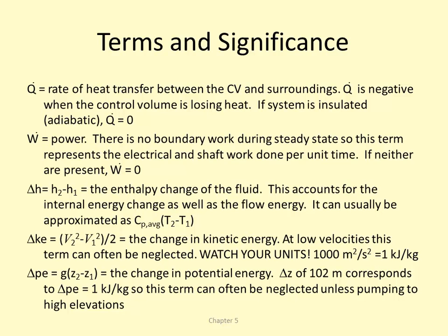Kinetic energy changes, again, watch your units. If velocities are not given, you can assume that you can neglect it. If velocities are given, then you have to calculate it. And the same thing goes for elevation changes as well. If they're given to you, calculate it. If they're not given, assume that it's negligible. Always, always, always keeping track of units.